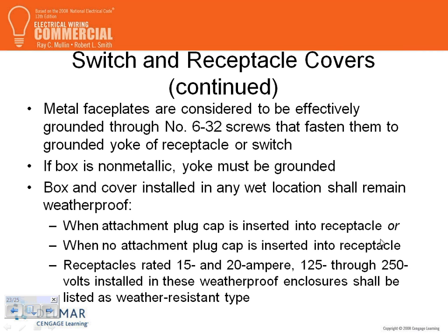Here's one thing I want you guys to remember because it might be on the test. Metal face plates are considered to be effectively grounded if you use this size of screw that fastens them to the grounded yoke of the receptacle: 6-32. So if you attach your 6-32, it's considered grounded if it's a metallic box. If it's a non-metallic box, who cares? You don't need to ground it. Okay.